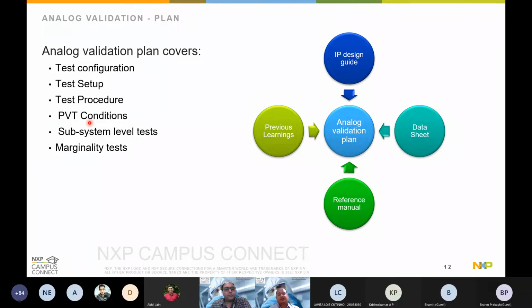But if I now use the whole subsystem, let's say I have the ADC which is triggered from some other unit, I have the DMA and so on. So the whole subsystem is now in the picture, and this may affect the electrical performance of that module. This is how the customer would also run the module, in the application board. So these subsystem level test cases actually make a lot of sense there.